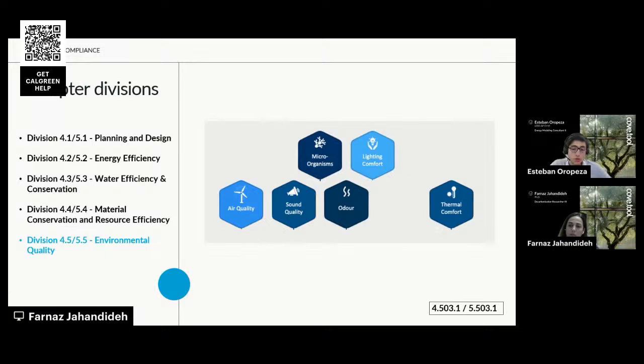Make sure that your construction site is equipped with vapor retarder installed over gravel for capillary break, and that needs to be thick enough and taped off. Also, make sure your bathroom fans are Energy Star certified, and fans must also be controlled by a humidistat on wall or in unit for 50 to 80% relative humidity, unless you have whole house ventilation. You also need to include your heating and AC systems, all the details there, and calculations in the drawings to show compliance with the energy code.